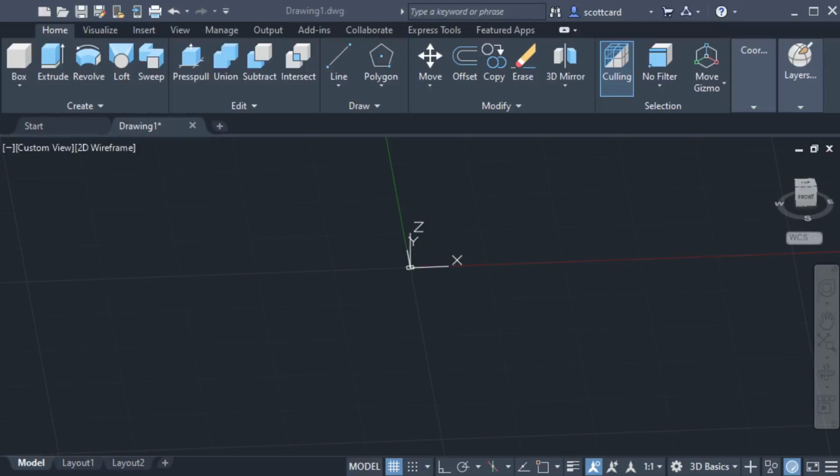And so what I've done is I've gone to my data sheet. I found the hex nut, and it's a 20 millimeter by 1.5, which is the thread. And I see that it has a diameter across the flats of 26 millimeters. And so what I'm going to do is start by creating the hexagon.